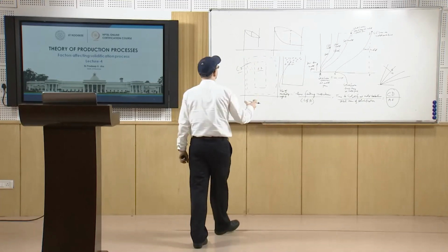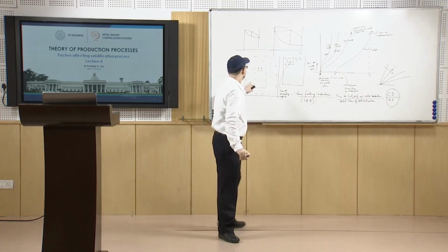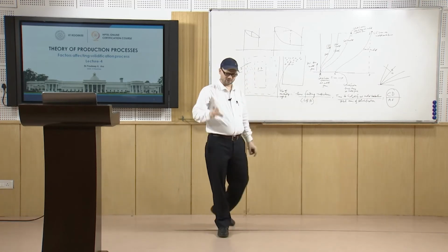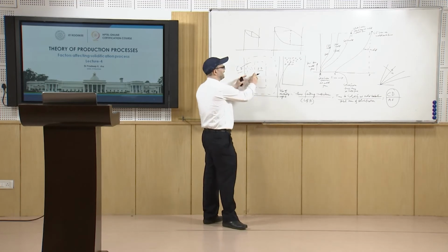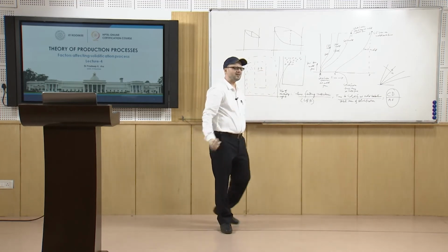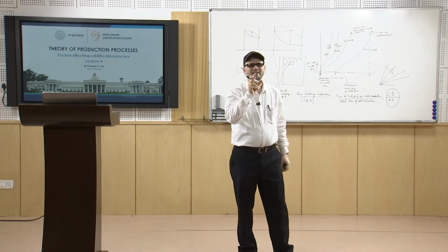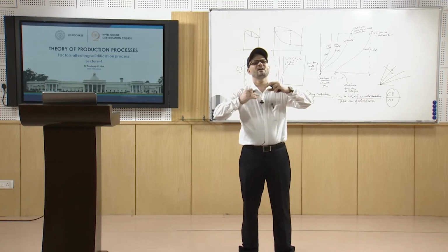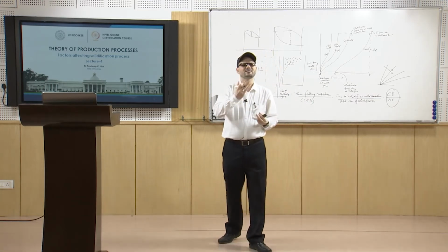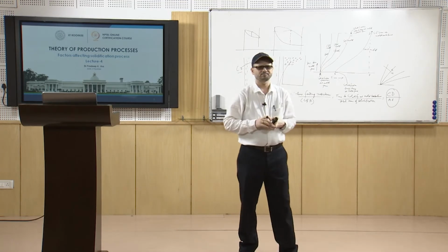So, with more superheat, because of the larger temperature, the growth of these columnar dendritic structures will be more predominant, and this portion will be more, making the equiaxed structure in the center less. So, that is why it is inversely proportional to the effective superheat. Superheat being more, the ratio of equiaxed to columnar grains will be lesser.